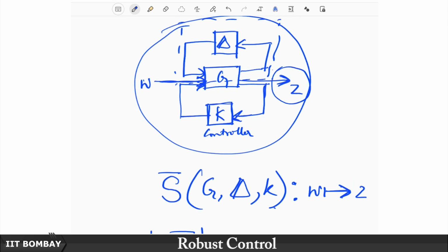So, something that you are very familiar with in an undergraduate course: what sort of a signal do you want to see the influence of which you want to basically eliminate? In that case we typically take this Z that you see here. This Z is typically like the steady state error signal. So you take the Y and you take the reference, so Y minus R is your error. So your Z could be that error signal. So Y minus R should be minimized subject to the application of disturbances and noises at different parts of the closed loop.